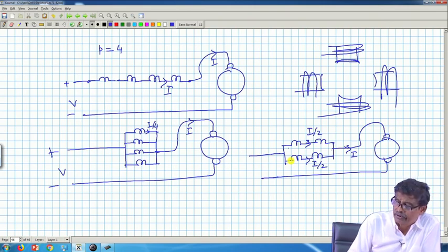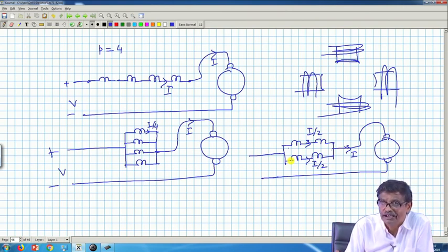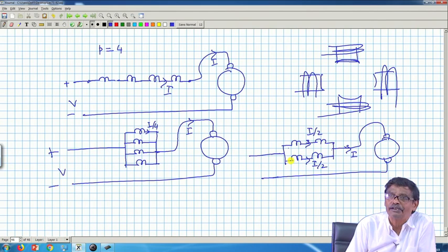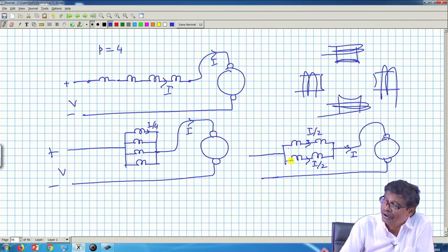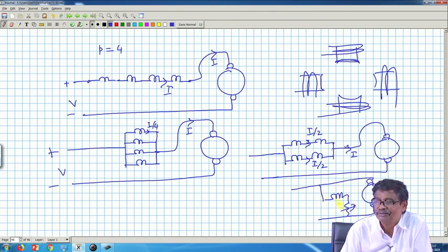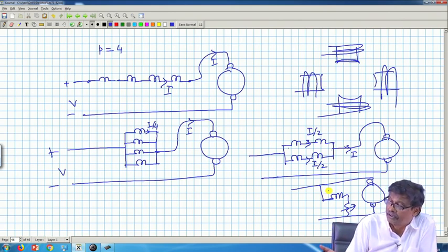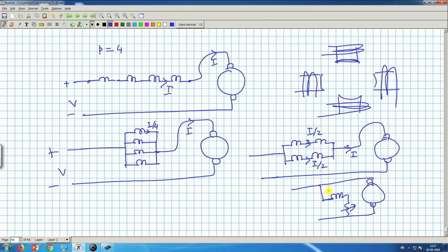One of the nice ways of doing it is this way, but not like a smooth field current control as we did in case of a shunt motor. In shunt motor, the connection was like this, and this is the resistance we controlled to decrease the flux per pole, that is all. But here, in discrete steps, some 3 speeds may be possible, 1, 2, 3 levels of speed control can be possible. You must keep this in mind.